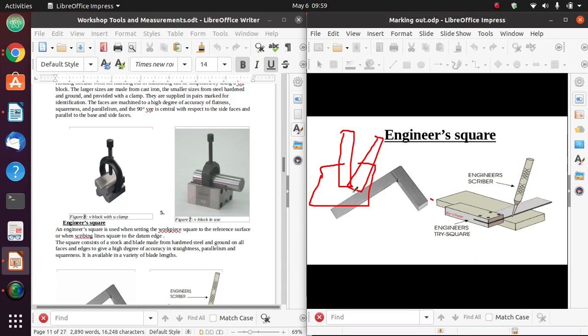I do not want to drill a hole that goes crooked. So I use this tri-square to test for squareness and to ensure that these lines I'm drawing, and the tools I'm using, are perpendicular to the reference edge, to the datum.